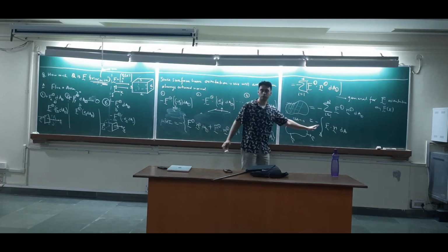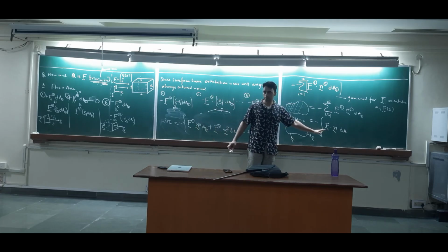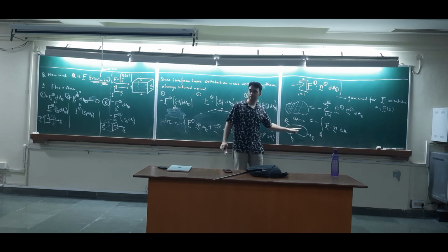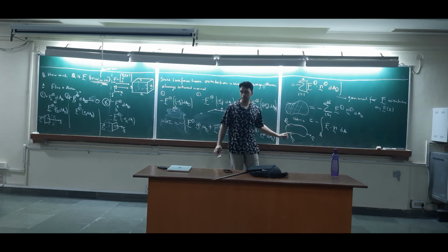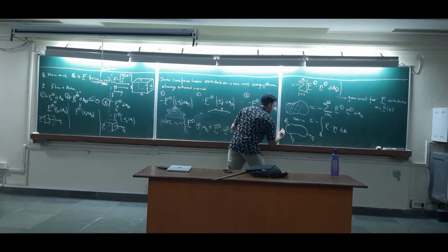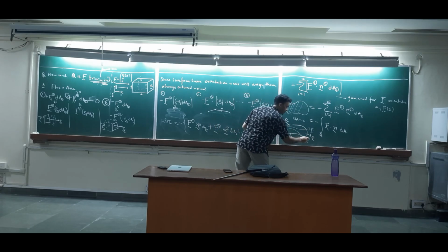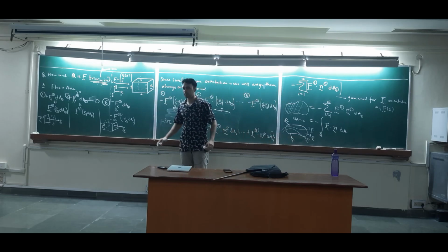This is cumulative of all the surface elements. Yes, but inside the integrand, it is at each arbitrary surface element. Yes, but at each arbitrary surface element, we are taking the dot product of the flux F and N, yes. So that only sums the contribution from the flux that is pointing in the direction of the normal. Yes. Yes. Just like quantities transported, like shear or something, for which we will come to the shear part.